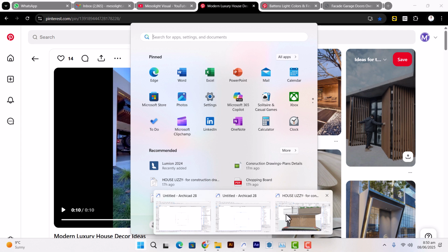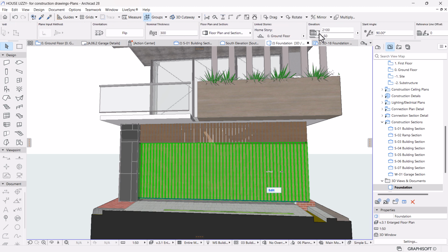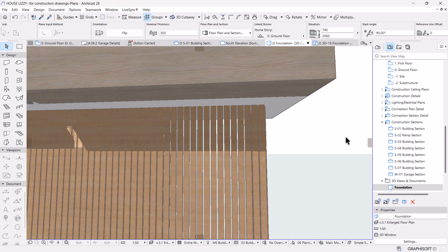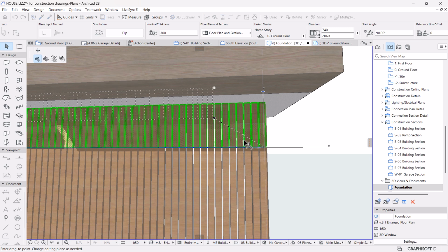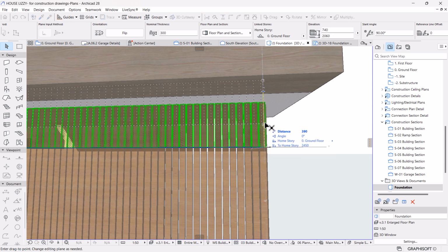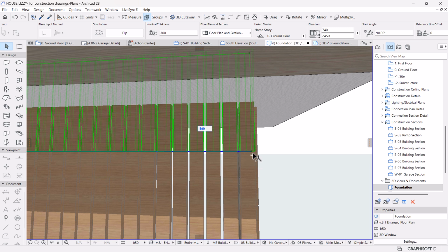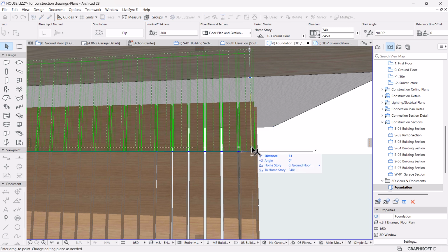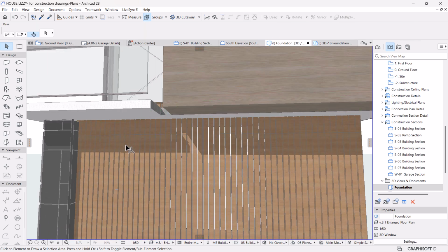So let's go back and change that. That means the total height for the door should be 2.5. So I'm going to change this to 2,500, and this will be the remaining. Let me stretch it, or just Control D to move it to the top like that. It looks too perfect, so I need to create a gap to represent that line of the garage door. So I'm going to move it by maybe 2. Yes, now we have this line.